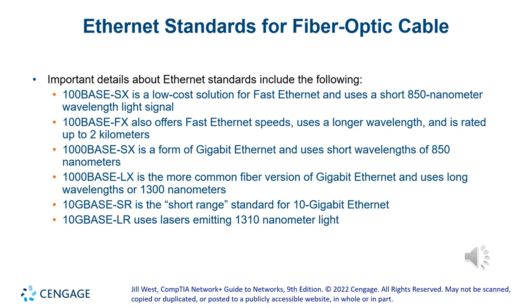match. There's no way that you can have an 850 on one end and a 1310 on the other end, because they're not going to talk to each other. It's like two different frequencies. It's kind of like your TV sending you channel 10 and you're tuned on channel 4. You're like, I'm not getting anything. Well, of course you're not. You need to be on channel 10. So they need to match. If they don't match, you will not be able to communicate.